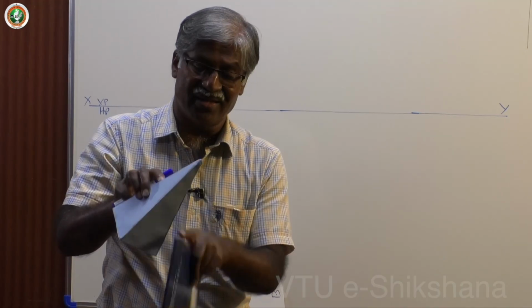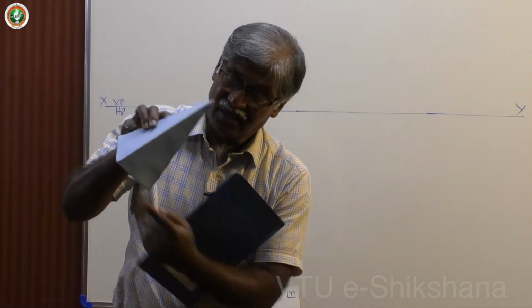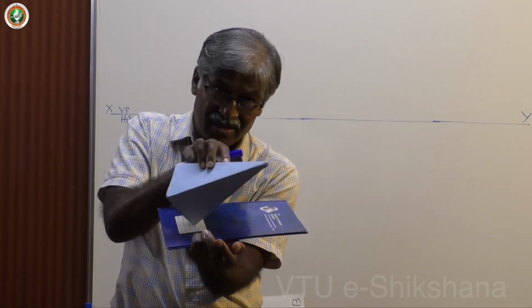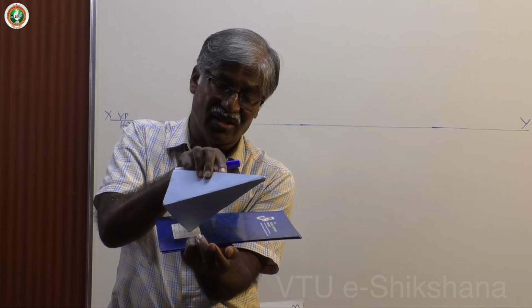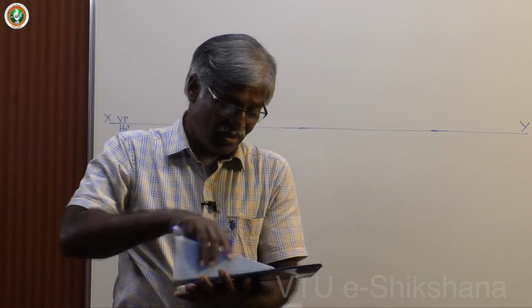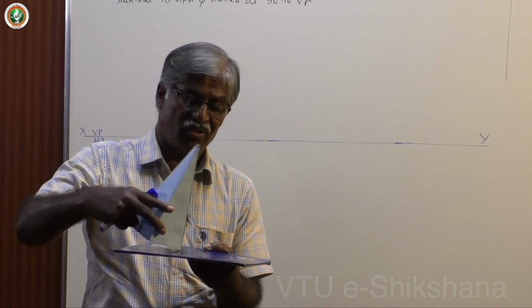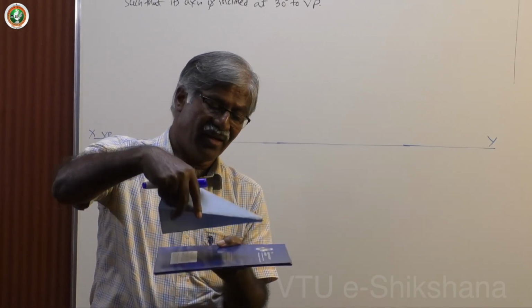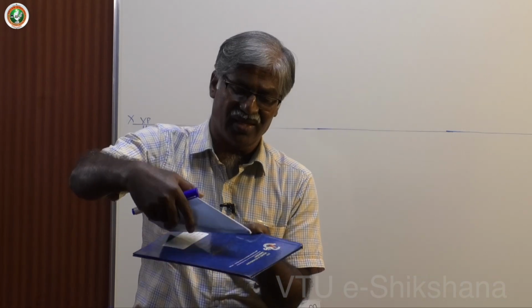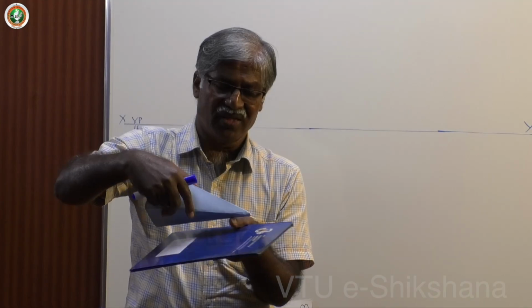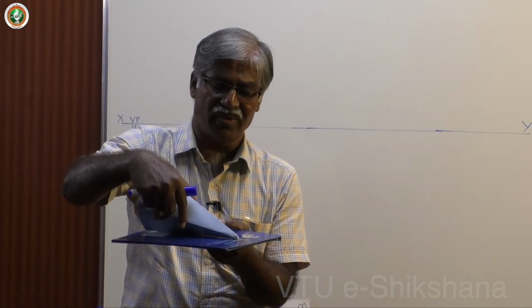See, this is the slant edge, this is on HP, and the two sides make equal inclination with HP and also VP initially. In this case, it becomes different if it gives inclination to VP for the axis. Now, for the second case, the initial position is corner position, then incline, and then you can see the slant edge on HP. In the previous case it is a slant face, the completely triangular surface on HP. Here the longer edge, in prisms we say longer edge, here the slant edge is on HP for that corner condition.